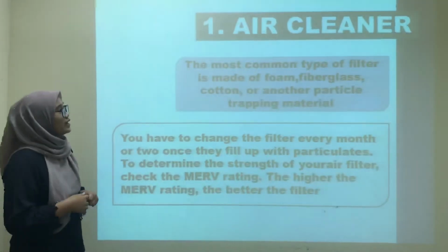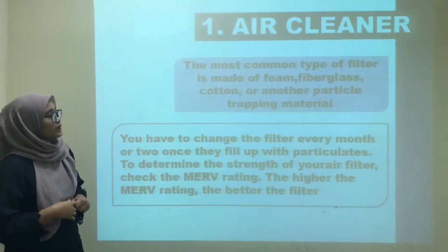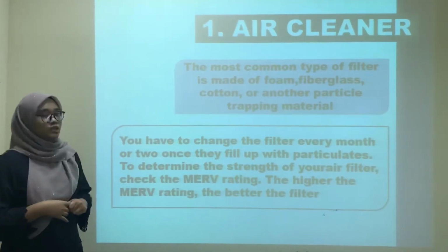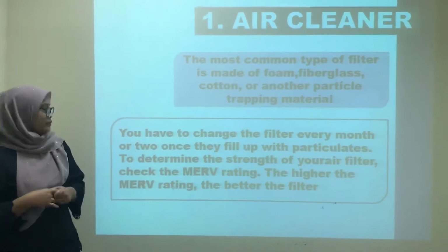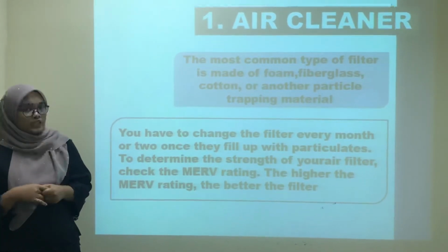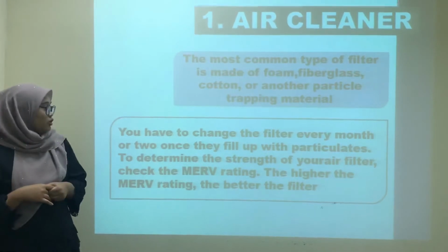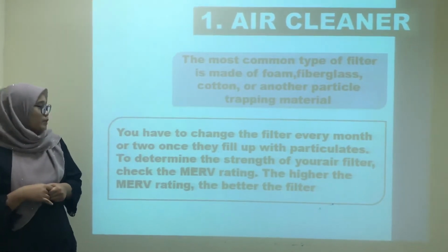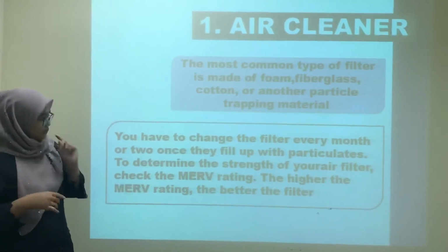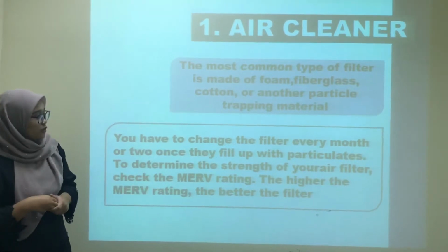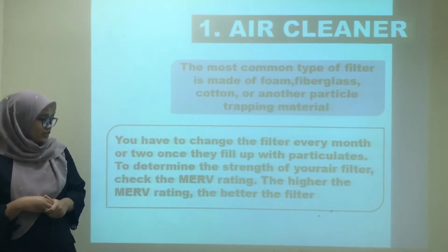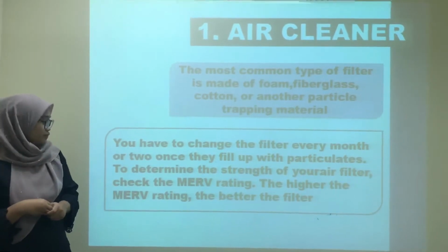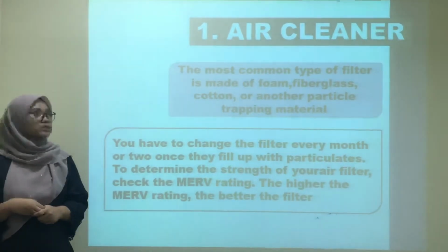First, the air cleaner. The most common type of filter is made of foam, fiberglass, cotton, or another particle-trapping material. You have to change the filter every month or two once they fill up with particulate. To determine the strength of your air filter, check the MERV rating. The higher the MERV rating, the better the filter.